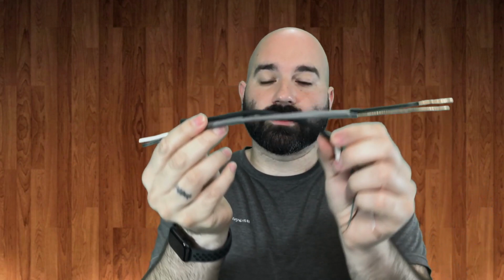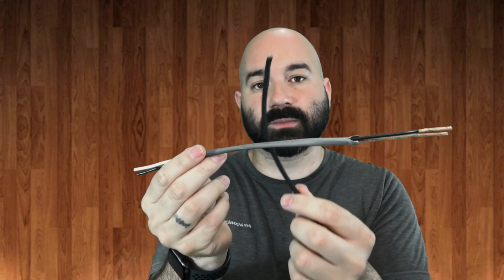And so rather than having it cross over in a lazy X pattern, have it cross over as perpendicularly as possible so that you minimize the contact point to have as little surface area as possible to minimize the EMI.